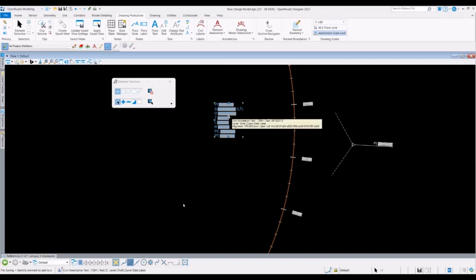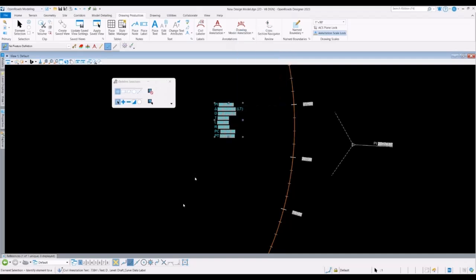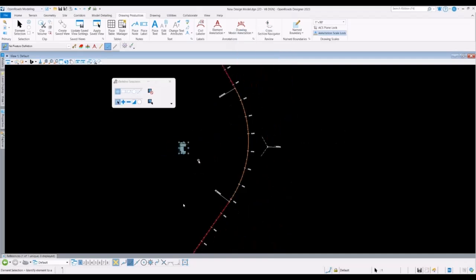And now when I go ahead and manually move, or if I want to retain the placement of this text, from the quick properties, if I click and hover, that little drop down at the top of the properties window is now made available from the manage modification toggle, right? So I set that to relative, I believe.